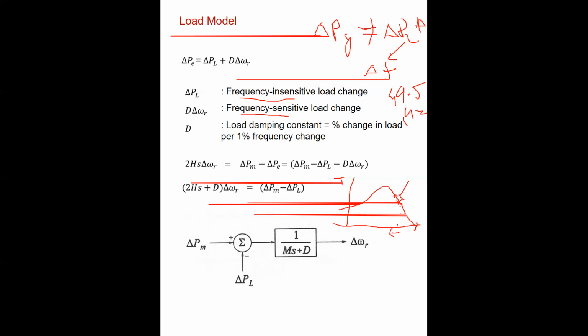So what is happening here? You see, effective load has increased, but because of the drop in the frequency, the torque of the motor has changed here, right? This is developed torque. The developed torque of the motor has changed. So what does this mean? This change in the torque is basically something like the motor having a positive effect of generation in the system.